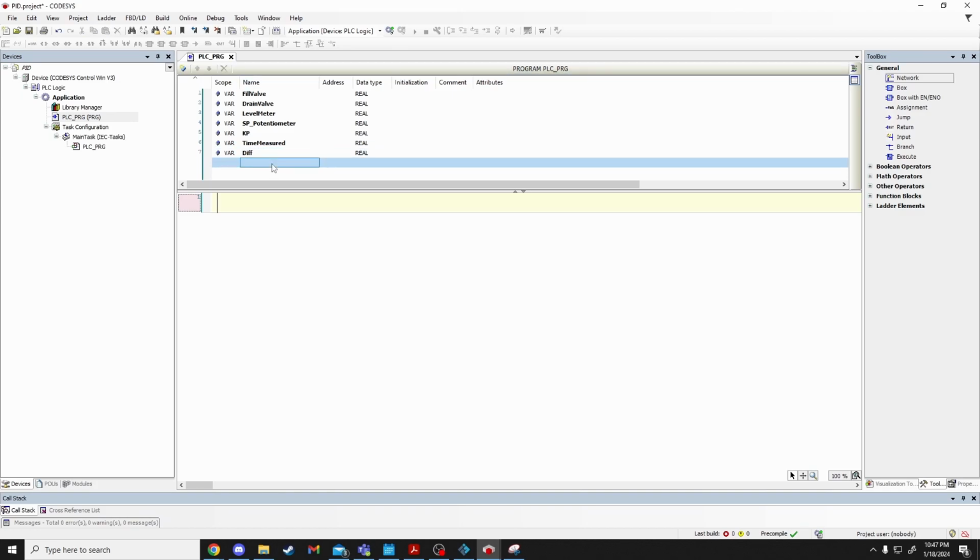And the differential is going to take the derivative of the function based on a certain measurement time, and that's going to help correct for the slope, give us a nice approach angle into our desired value. We're trying to avoid overshooting and oscillations. We want to keep the steady state error relatively low, but we are going to have some.